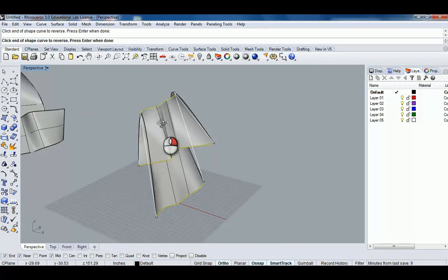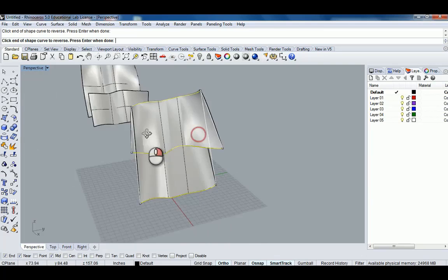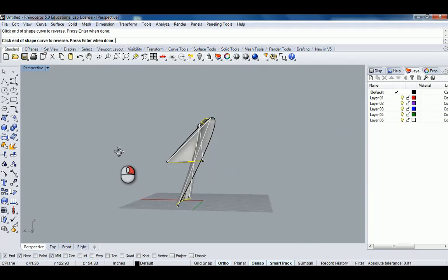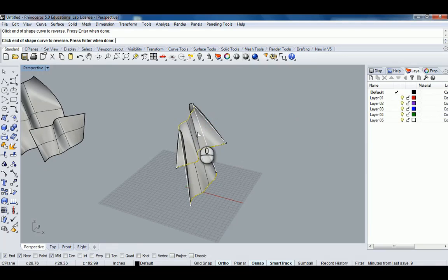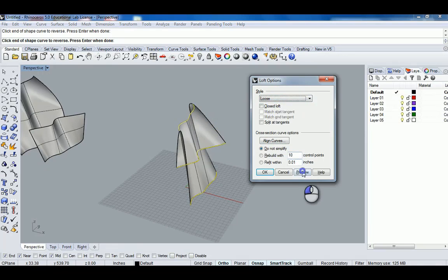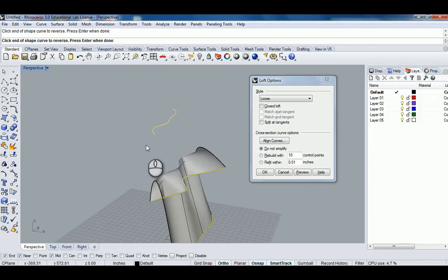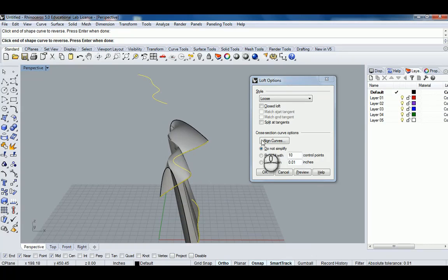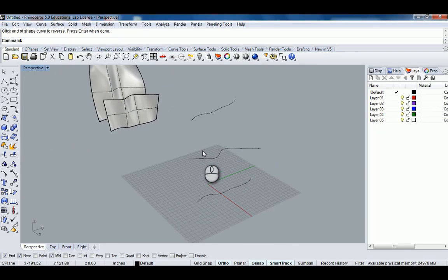But in this case, that is not the way that these lines were set up to be extruded, right? So if I were to try to loft it here, we have overlaps of the surface. It's messy. It's not really doing what I want it to do. I could see what these other commands let it do. So the loose command in this case is using this second line as a loose reference point to pull the surface up and then back down. The tight one is going to try to hit every point on each line, and it's just kind of a mess. So the order in which you choose the lines is important.